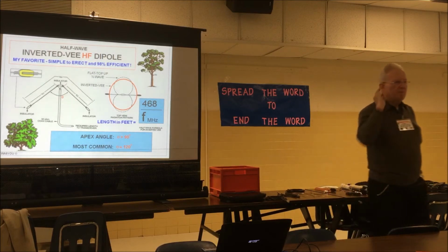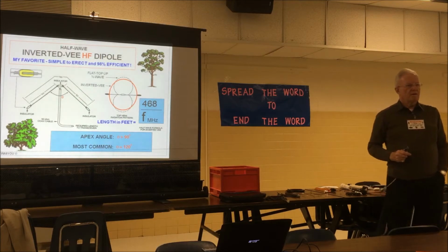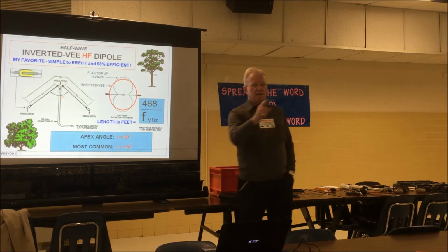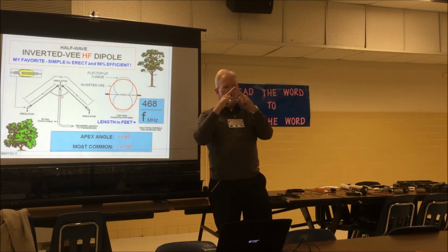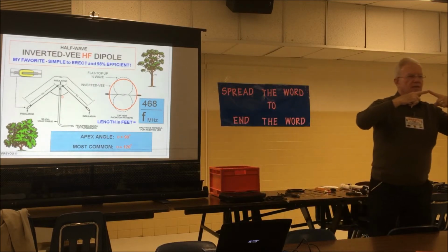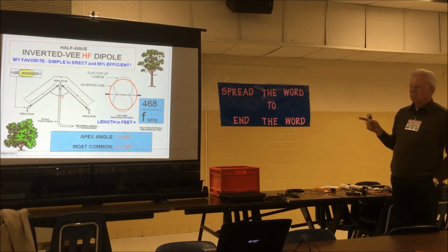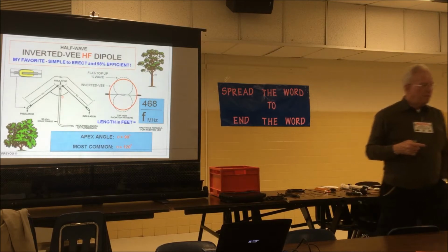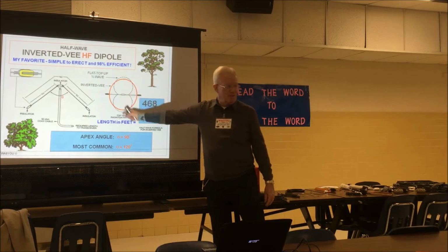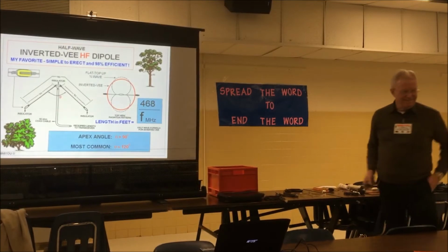Yeah, you said yours go down to about 7 feet up. But what's optimal for something like that? Oh, well, greater than 90. Don't ever let the inverted V angle be less than 90 with each end down there. Optimal angle? Do you want to get it as high as you can? Yes, absolutely. What will happen if the angle is less than 90? Oh, it screws up the pattern considerably and the impedance. Yeah, mine's 120. Man, it's just perfect.